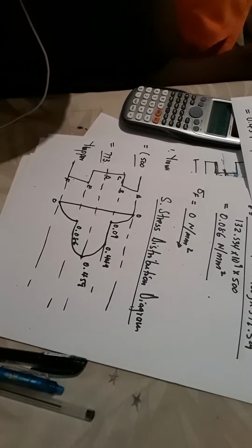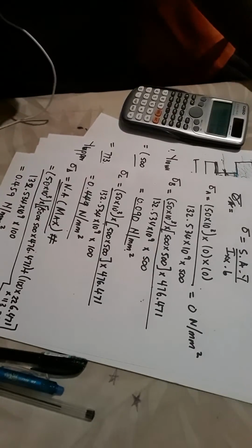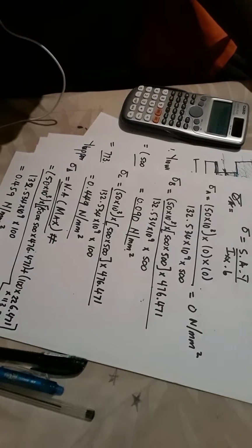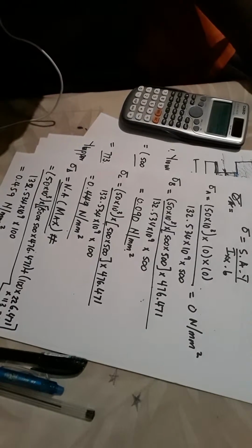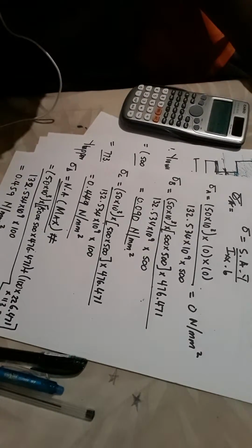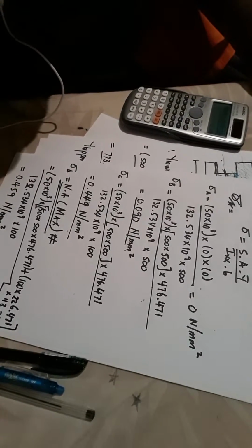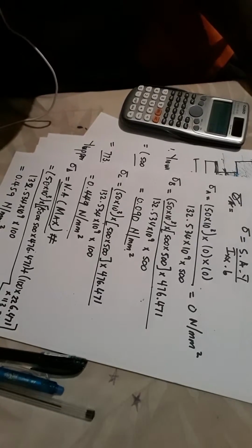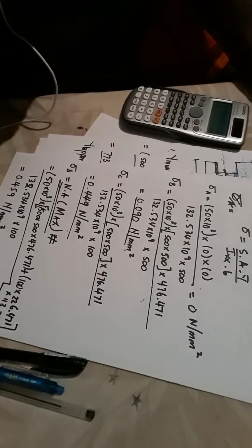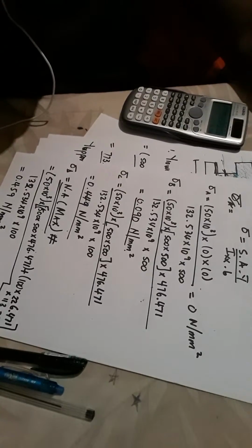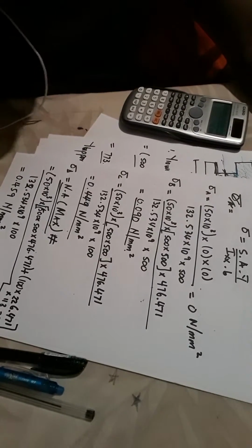So guys, this is how you deal with shear stress. When they say calculate shear stress at any point in question, you simply follow those steps whereby you calculate y lower, y upper, and then you calculate IXX. After you've calculated those, then you can calculate shear stress at any point in question.